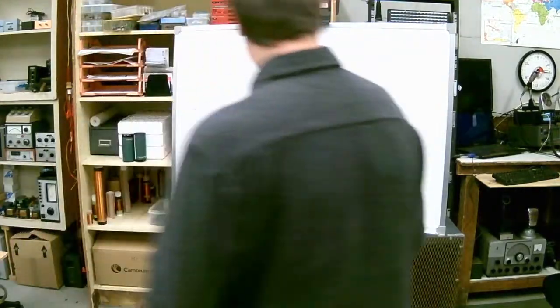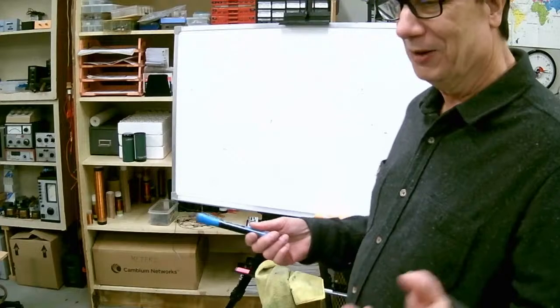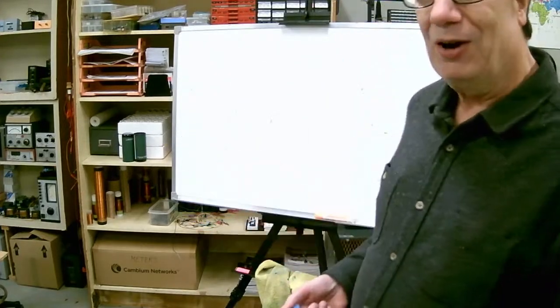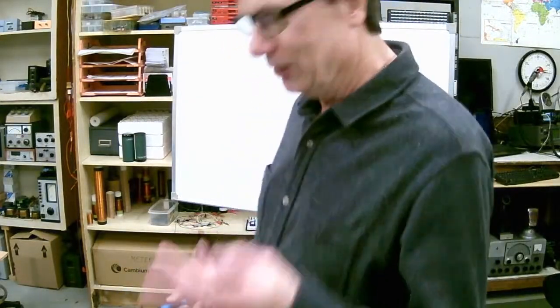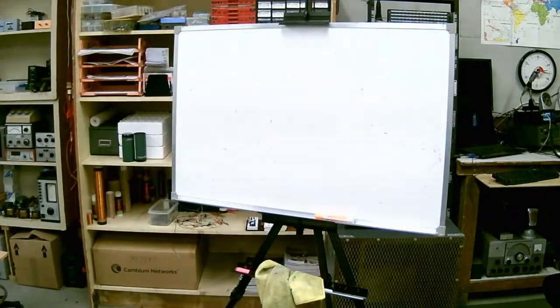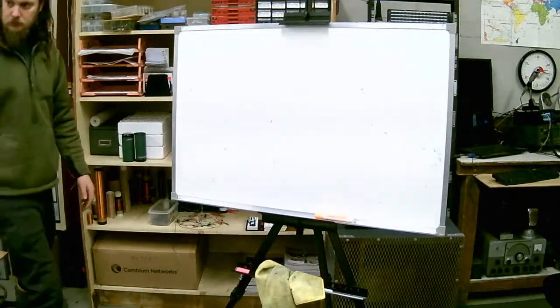Okay, now, we've built some audio amps before, well, they were DC amps, so basically audio amps. And an RF amp is just an amplifier that's tuned to a specific frequency. Now we haven't talked about detection. So the first form of radio was actually AM, and it's very fortunate that we have a very strong AM station here, because you can see our AM signal right here. We got a carrier, and then we got the modulation on top of it.